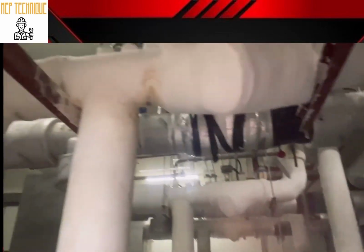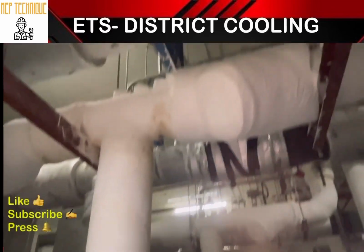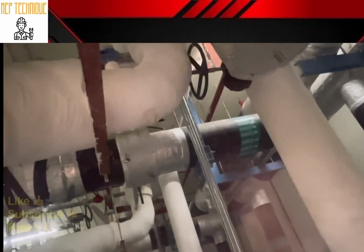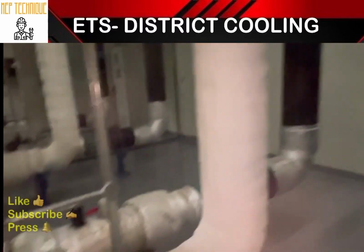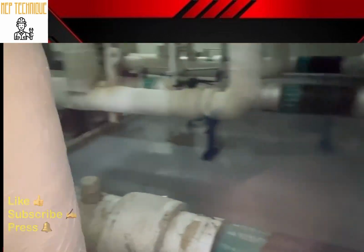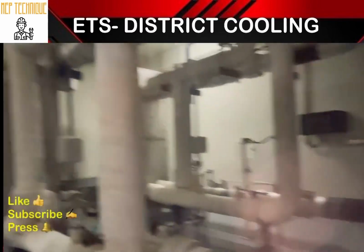This is the secondary supply, and there is the bypass line. In the event of any maintenance, or as per requirement, we can open the bypass line. This is how the chilled water is distributed from the heat exchanger. Now we are moving to the PLC.